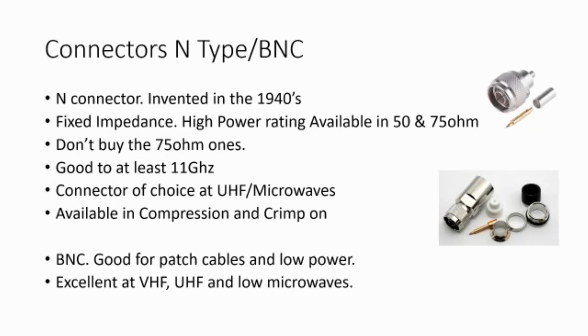BNC is a very similar type of connector, available either in a compression or a crimp-on. It's a lower power connector than the N type. It's excellent at VHF, UHF, and the low microwave frequencies.